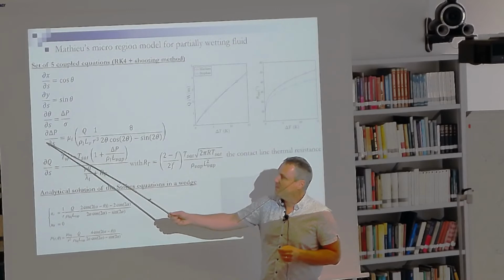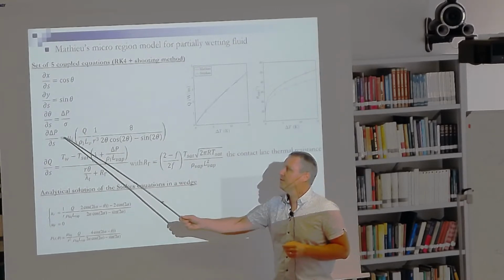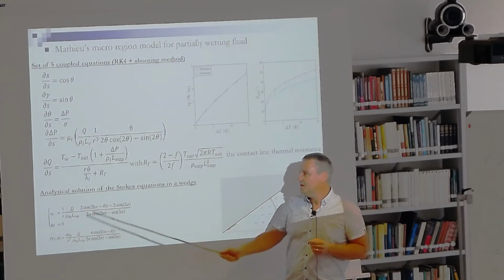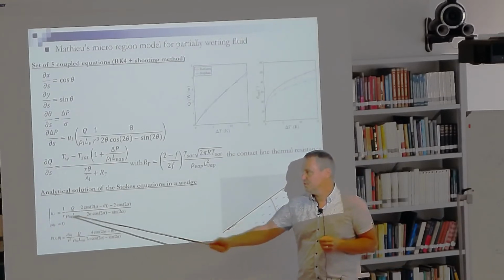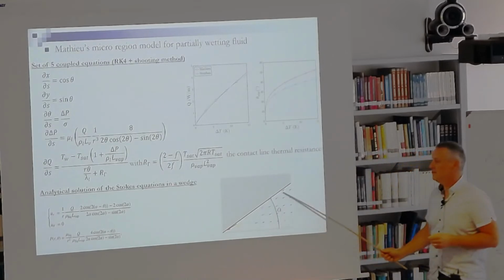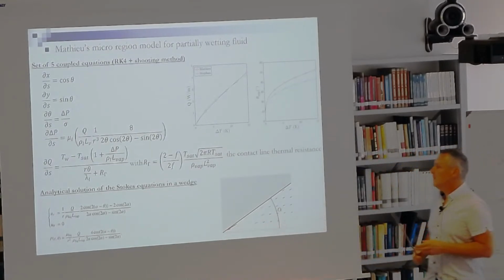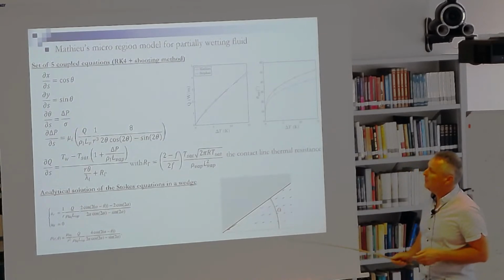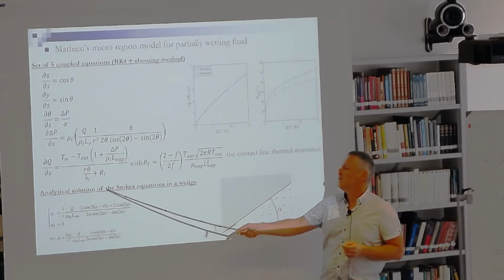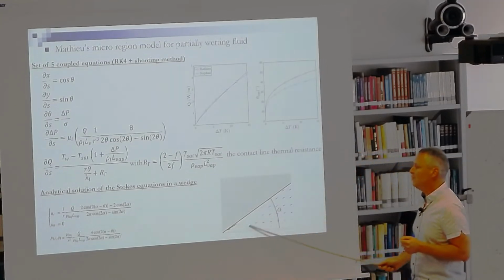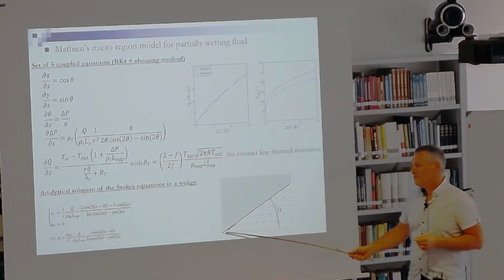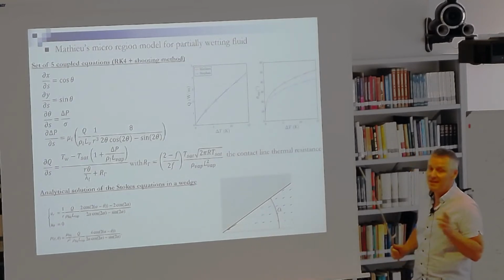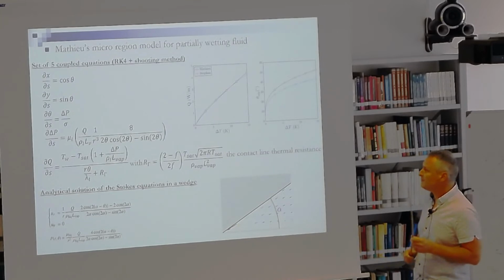This one comes from Stokes' equation, for which we have a given pressure distribution related to this velocity distribution in that kind of configuration. This is the flow obtained from the analytic solution of the Stokes equation in a wedge, with a source term of mass at this point and a sink term of mass at this point.